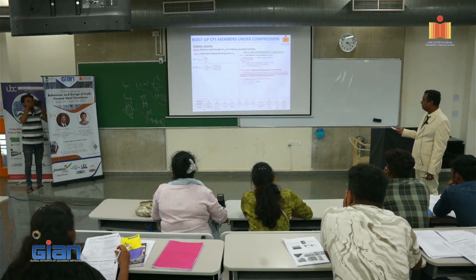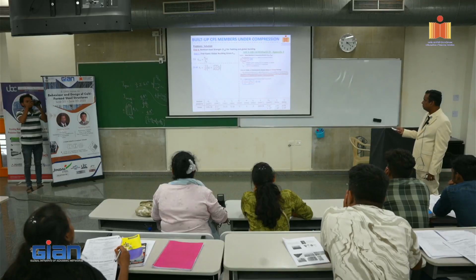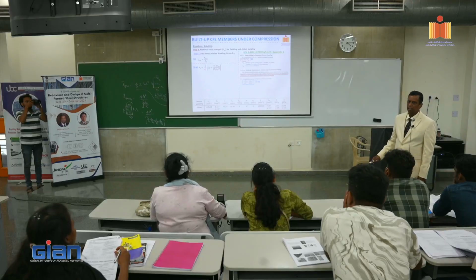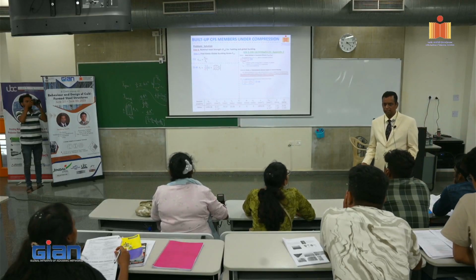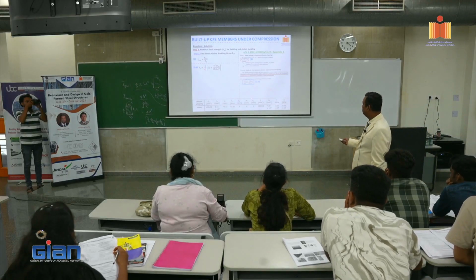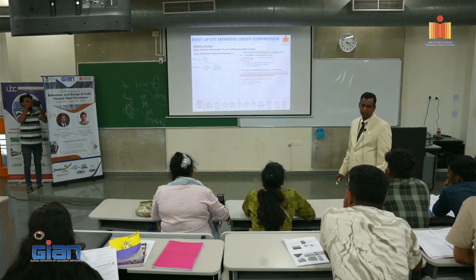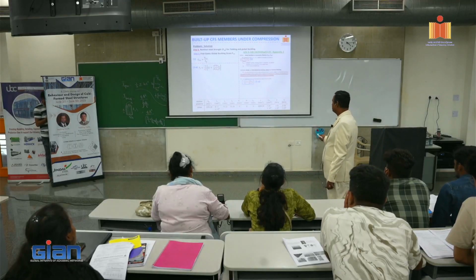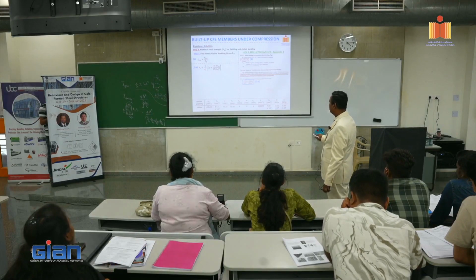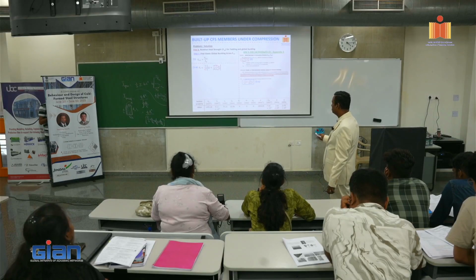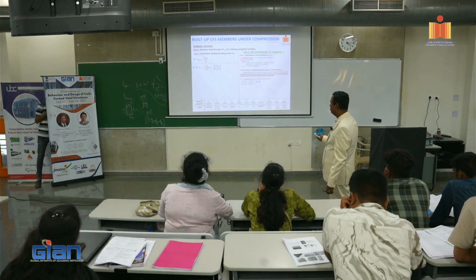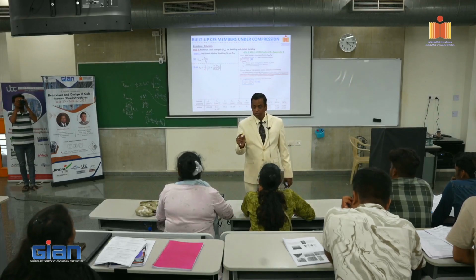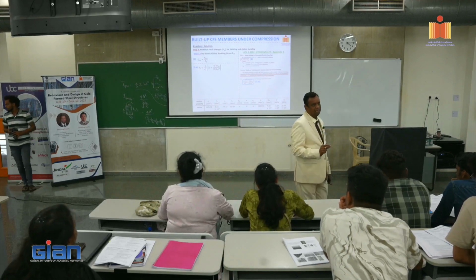It says for doubly or point symmetric cross section subjected to torsional load. What is doubly? It's an I section. Here we have two C channels, so it becomes an I section back to back, right? What is point symmetric? Z sections, but here we are not dealing with Z sections, so we are dealing with only I sections. So this one is the equation for that, 1 by R naught square, G J plus pi square E Cw divided by Kt Lt the whole square. Here GJ is called torsional rigidity. What is E Cw?